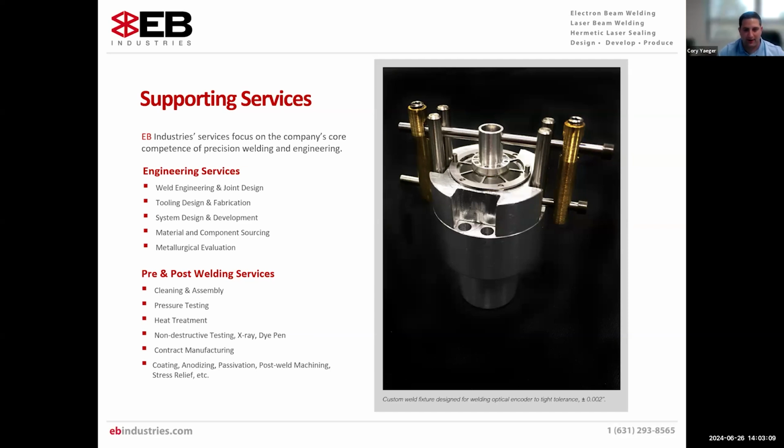See a question here about are our machines on welding on a single XY plane or are multiple axes supported? I would say both. We have machines that are capable of both. We have several machines that have CNC capabilities that have similar axes supporting, like 5-axis CNC machining. So we started off with mainly having single plane machines. And in recent years, we've been investing in developing our EB welding machines with CNC capabilities of supporting more than just 2 axes.